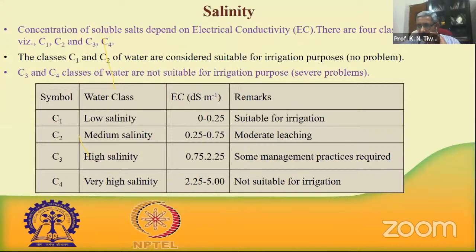The question, by Mr. Brajesh Tripathi, is: explain non-recording rain gauges. Thank you, Mr. Tripathi ji. The non-recording type of rain gauge is the Symons rain gauge. It has a 12.7 or 127 millimeter diameter funnel. Whatever rainfall occurs, the water comes through and is collected in the sampling bottle, and from the sampling bottle it is poured into a measuring cylinder. The volume of rainfall is measured with the standard gauge, and that value is given as the rainfall occurred in 24 hours. This is a very simple device, and it is used by IMD.